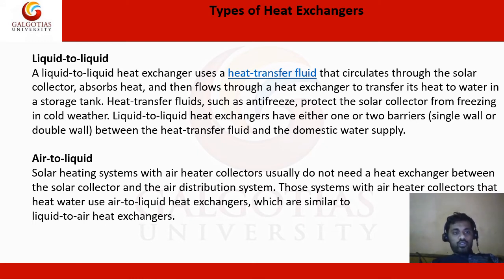In solar water heating systems we use heat exchangers to transfer the solar energy absorbed in the solar collector to the liquid or air used to heat the water or space. Heat exchangers could be made of steel, copper, bronze, stainless steel, aluminum, or cast iron. Solar heating systems usually use copper because it is a good thermal conductor and has greater resistance to corrosion.